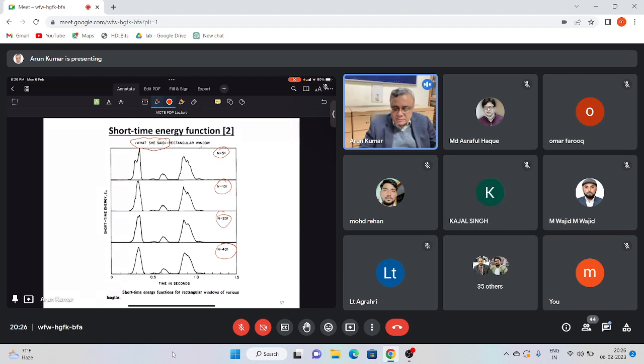or not, whether it is speech or silence, and secondly, if speech is present, then whether it is voiced or unvoiced. However, this by itself cannot unambiguously tell you whether it is silence or voiced speech or unvoiced speech, because these are overlapping segments. Sometimes if you have background noise, then the short time energy may not be very low, in which case one should not confuse unvoiced speech with silence.